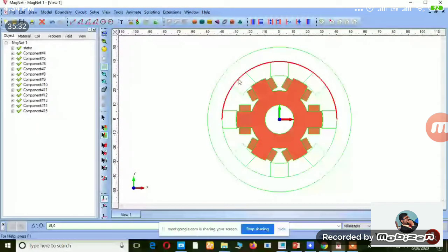there is a line which is joining the rotor poles as well as the back end of the rotor. I am just going to select the line also. By pressing the control button, we can select more lines, right? Again, I just go into the segment edges. Now I have selected the lines which are not needed in the rotor and now deleted them.